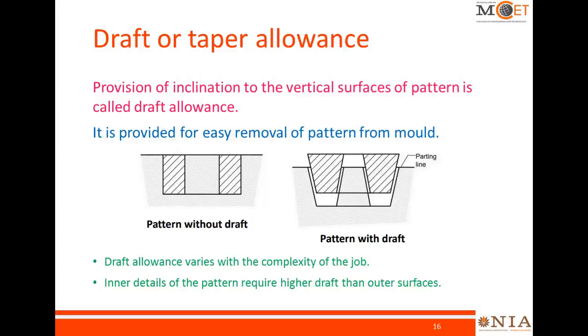And draft or taper allowance. So this is a provision on inclination of vertical surface of the pattern, called draft allowance. It is provided for easy removal of a pattern from the mold. So you can see here there are two figures given. The first figure is a pattern without draft. The second figure is a pattern with draft.